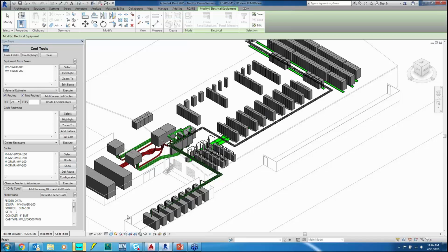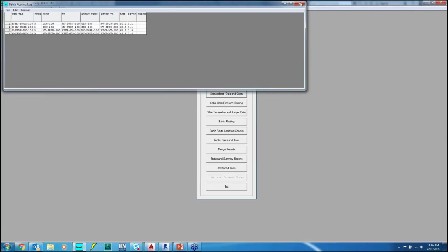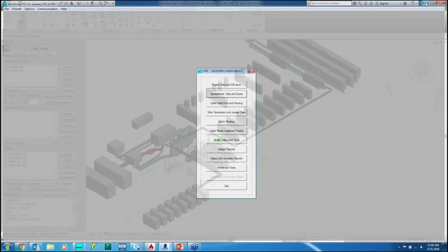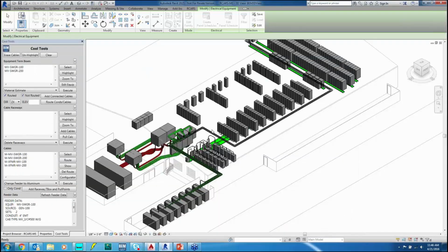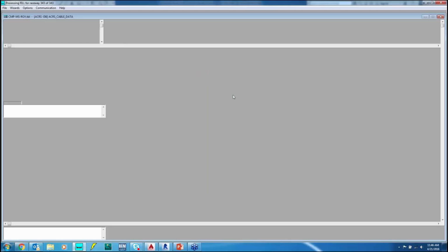The program will fire up, and this is the other screen I wanted to show you, and it'll show you the actual route length that it used for those particular cables. Now, routing 4 cables through a conduit is not terribly challenging, but let's take a look at all of the cables on this project. So this is my cable schedule interface here.